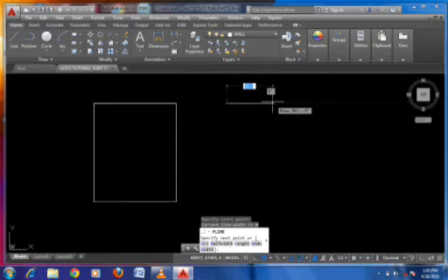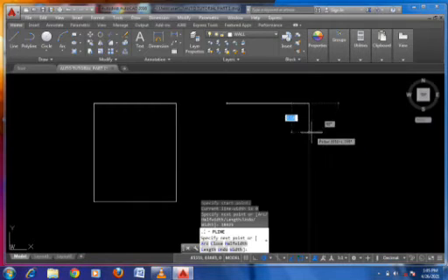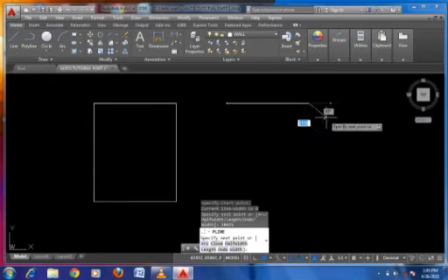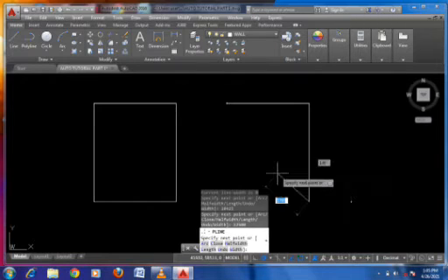Start your line on our horizontal axis. We want it to be 10,425. Press enter. In the polyline, you don't press escape because the line is a continuous line. You can just continue, whether you want to continue horizontally or vertically. You just change the direction. So I just change the direction now. I'll type 12,500, enter. You can see that.